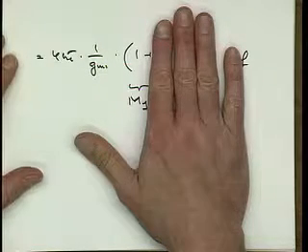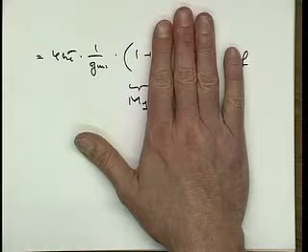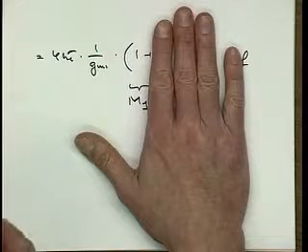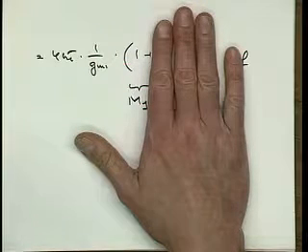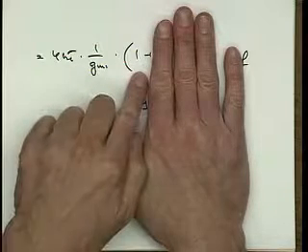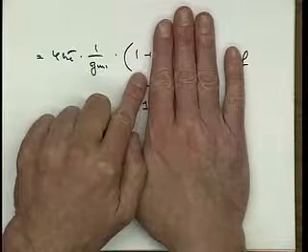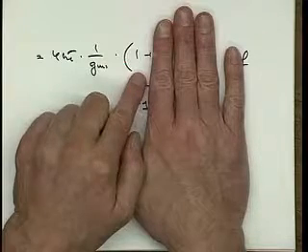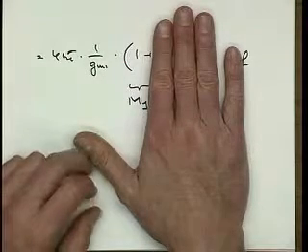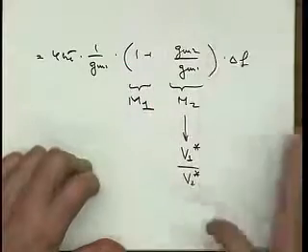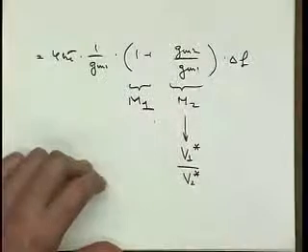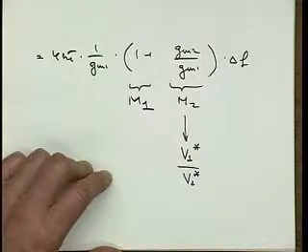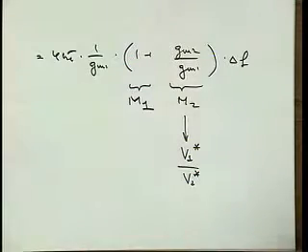So one figure of merit on how good a job we did building our amplifier is how much noise we added beyond the minimum that is required. Up to this, there is probably not much we can do. We can reduce this noise, but then we get rid of the amplifier. Not very interesting. So our job as designers is to make this extra term small. If it's unity, then we double the noise.